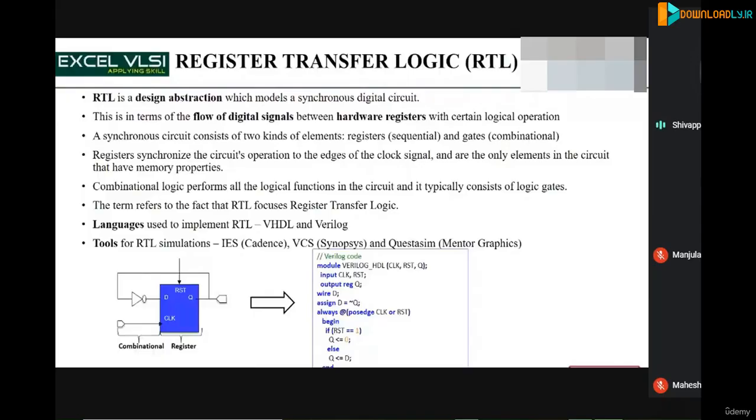Basically, here I have just given an example of code. I know you might have seen more complex Verilog HDL codes, and those are the things we will take for synthesizing. Now, if you synthesize this code, finally you should get one NOT gate and one flip-flop. These are also called standard cells. We talk about this: the NOT gate is a standard cell, and this flip-flop is a standard cell. So that is about RTL.